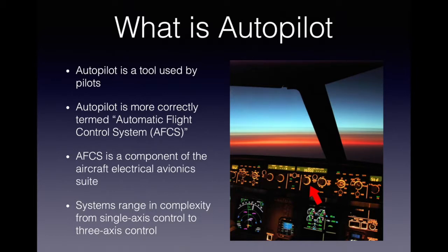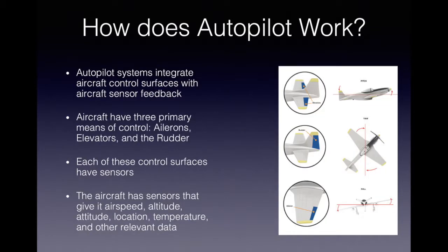This is a common feature in many aircraft, but can have varying degrees of complexity. Simple autopilots can hold one axis of control, while more complex systems can control 2 to 3 axes or even navigate and maintain a GPS course. Autopilot systems are responsible for taking information from sensors about the aircraft's flight dynamics and changing the required control surfaces to correct for any deviations from a desired input. A simple example of this about one axis of rotation would be changes in elevator pitch to control altitude.